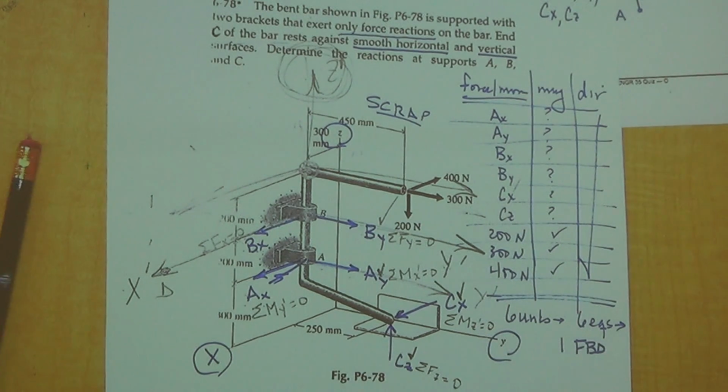It's kind of like the same thing when we were doing two-dimensional, where we would pick the point we were rotating about. There were two reaction points. That's right. We chose that point specifically so we would cancel out. Exactly. So what Chelsea's saying is in a 2D problem, you got to choose the point you wanted to find a moment about, and it didn't matter which one you chose. That's the same thing for Santiago. For a 3D problem, you could choose any line you want. I happen to call them x, y, and z prime, but they could be called anything.